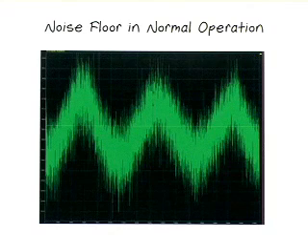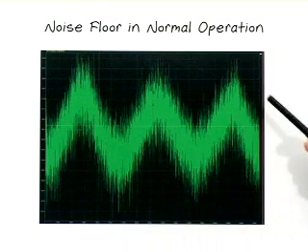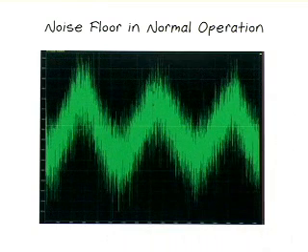Now I would like to show how digital feedback can manifest itself in the noise floor of an ADC. Here is a magnified screenshot that shows the noise floor of the LTC2261. Digital feedback typically produces a shaping of the noise floor as shown. In this case, the digital feedback causes peaks in the noise floor of about 3 dB. The layout of the LTC2261 demo board was optimized to minimize digital feedback, but still some is unavoidable.